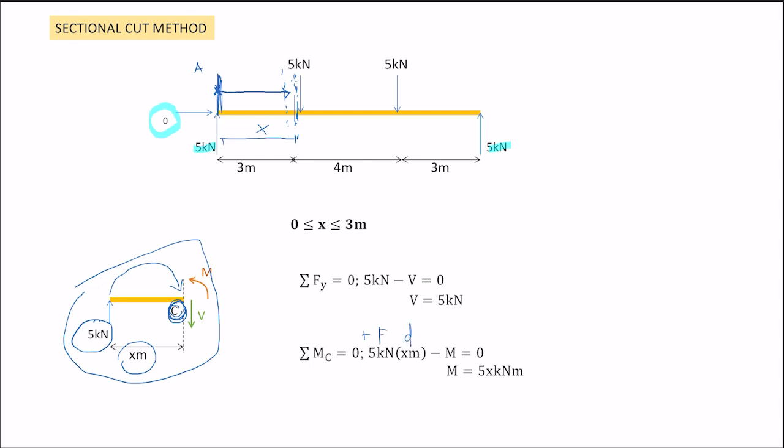And there is no other moment or forces acting on the beam at this section that we cut. The last one is this moment. By our rules, we take it counterclockwise, meaning it is negative, M equals 0. Simplify the equation and leave the X, because we don't need exactly a value.